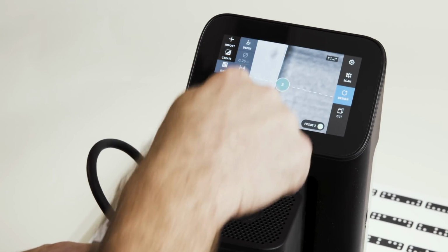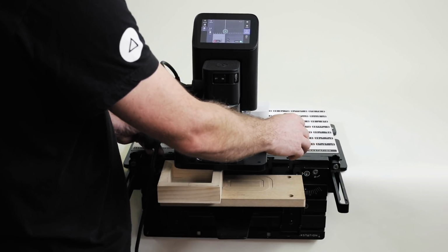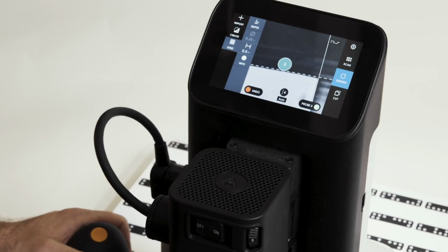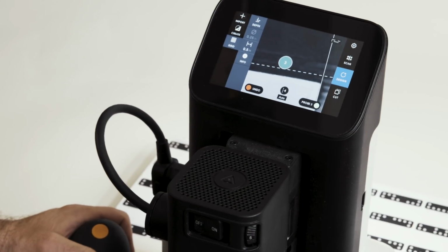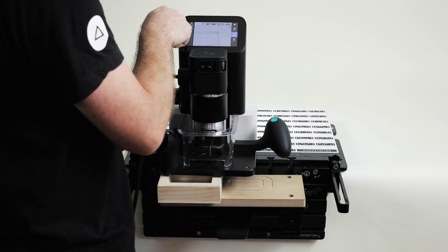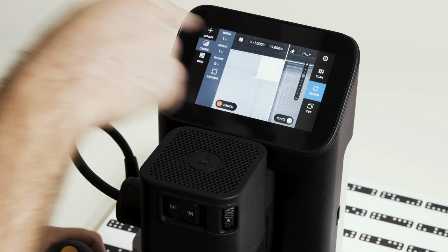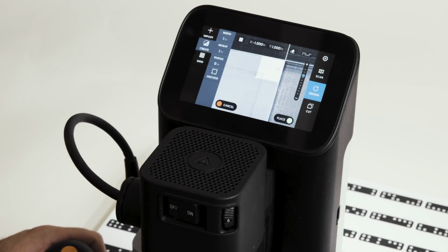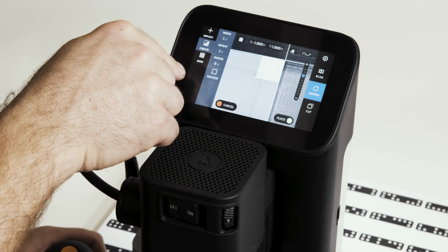probe again. It selected the right side of my probe, and then actually coming around the top has also selected the right side of my probe. So the first axis is technically X, and now I'm defining Y. So they're flipped 90 degrees, but it still enables me to place shapes, as we can see here, at very precise increments, very accurately aligned to the edge of my stock, and also oriented perfectly.